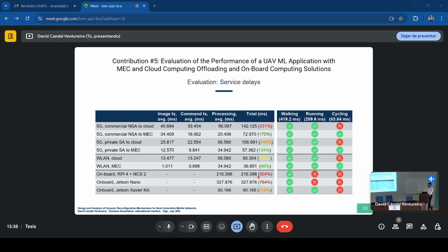I would go for the Raspberry Pi with the Intel NCS2 because, first, it matches the target required latency, and on the other hand, the power consumption of this board with the NCS is similar to that of the Raspberry Pi with a 5G modem. And you do not need to get a mobile data subscription for that.